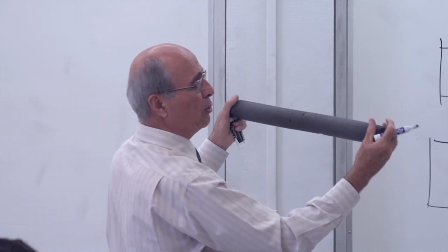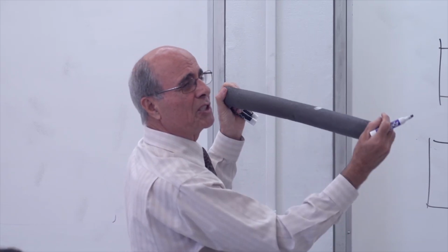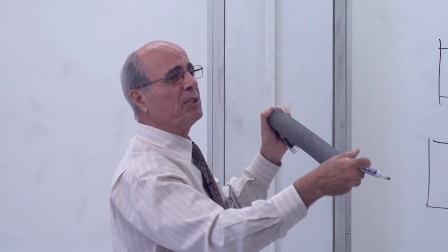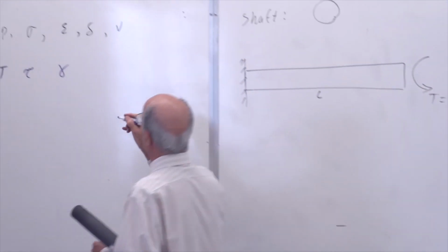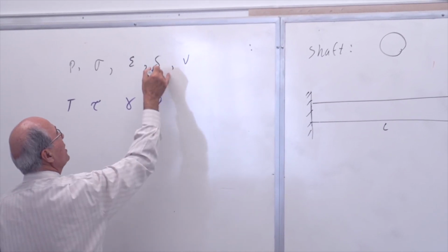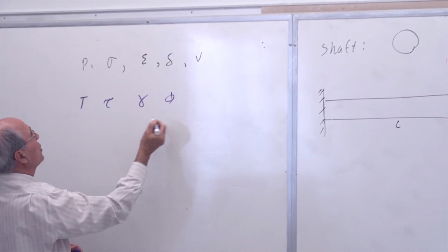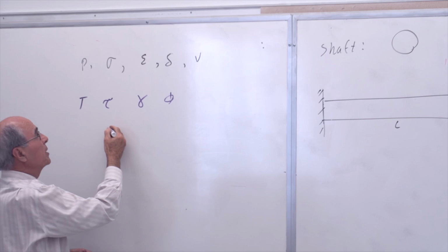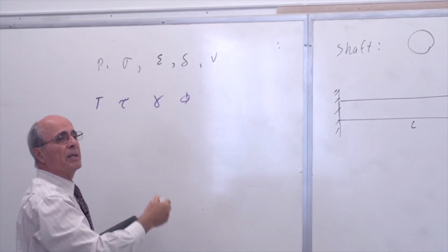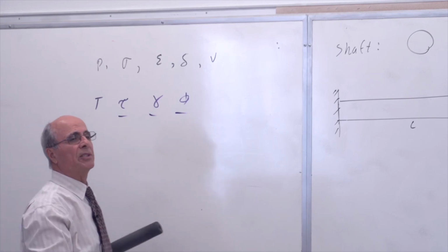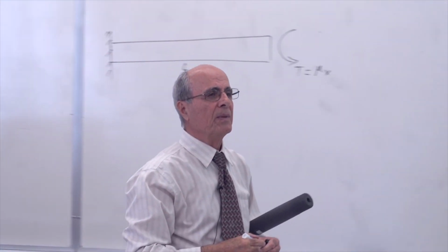The way I do it, this is very plastic, so you can see this is turning 10 degrees. But if it's steel it's going to turn half a degree, yes or no? Therefore, I'm looking for all of them. Phi. So suddenly delta becomes angular rotation, stress becomes tau, the force becomes torque, and the strain becomes gamma, and all of this should be answered one after another, yes or no?